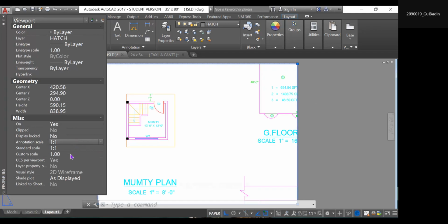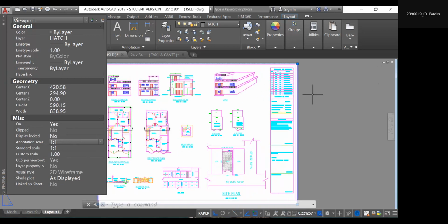But if you go back, or you just undo your scale which was the 0.22 custom scale, or you can select scale to fit, because your whole sheet is not to the scale, so you just select scale to fit, so it will get you back to the original setting. So just lock your diagram, lock your display, lock, and close it.